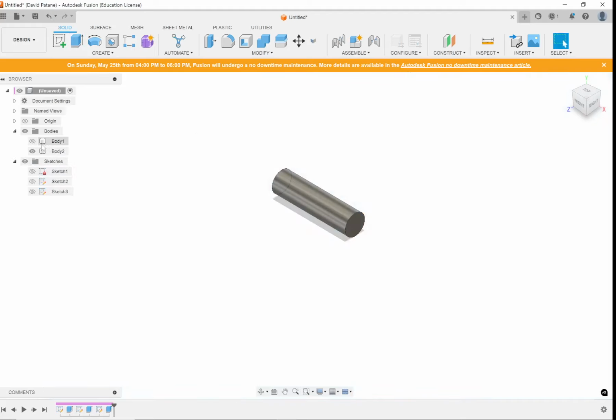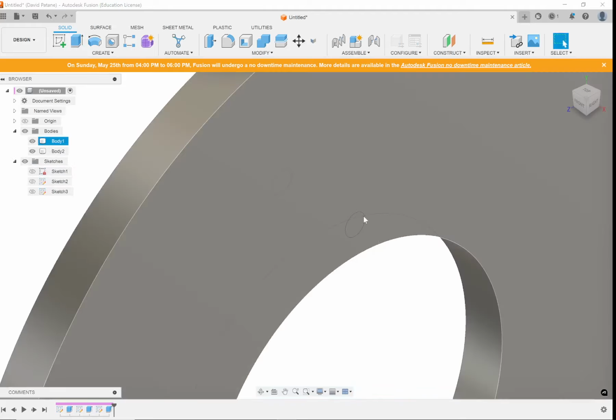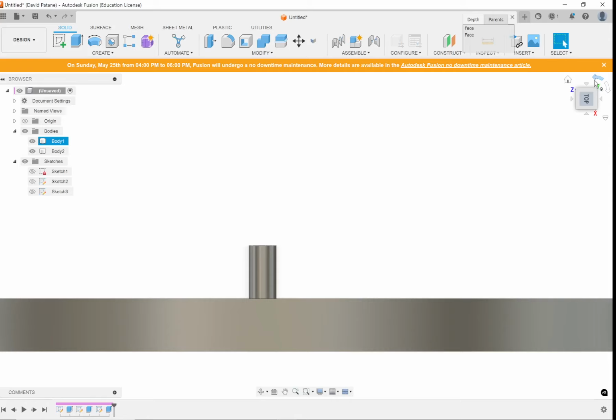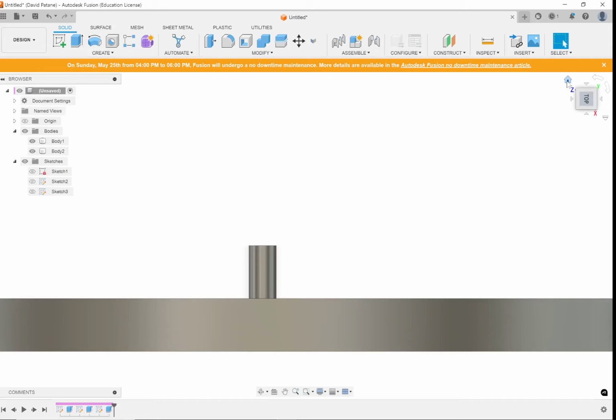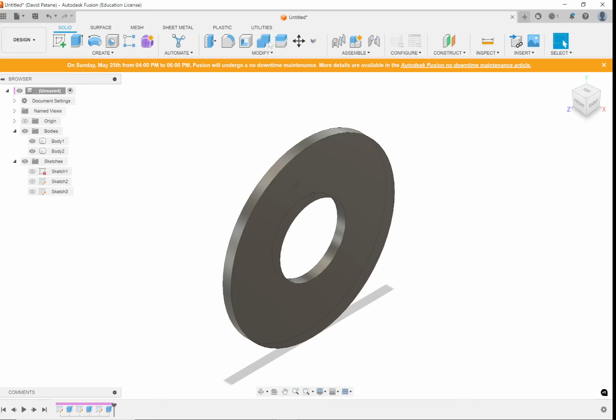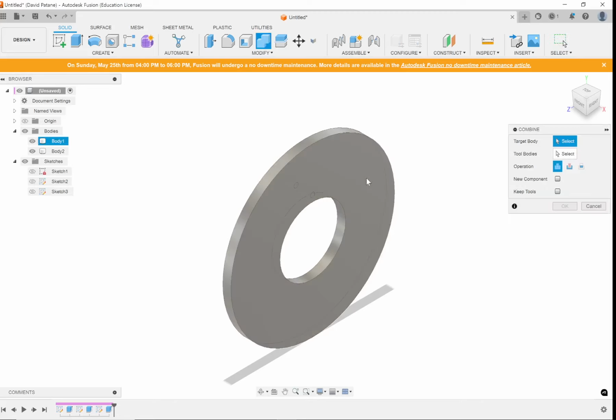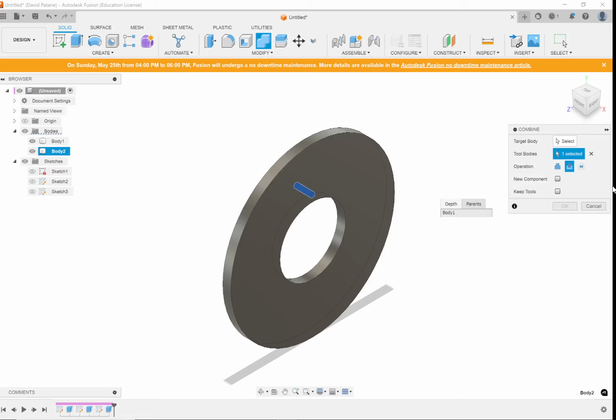I want to drill that hole into the body that I have there. And if my CAD... okay, yes, so I want to drill that hole through that body. And I can do that in my CAD software. I can go to modify, I can select this body and I can say this second body, which is the hole, and I can say remove, and then it's going to